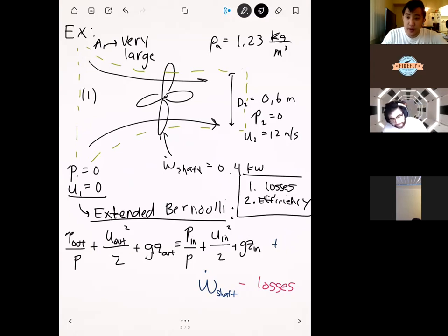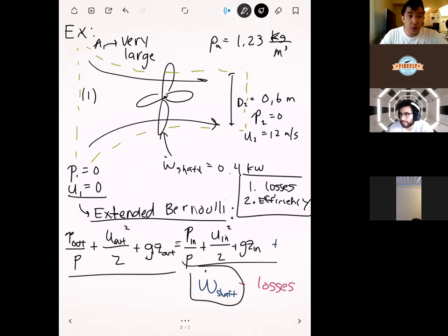So the question is, what did we apply to get the last two terms? That was from the last lecture. What we did basically was we took our control volume form of conservation of energy, took our RTT and applied it to energy, and then we connected it to the Bernoulli equation. Once we connected to Bernoulli, we were able to make a one-to-one connection with a lot of these terms. But what we had left after that was W dot shaft, which comes directly from our RTT for conservation of energy.